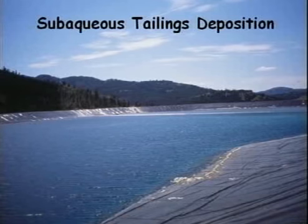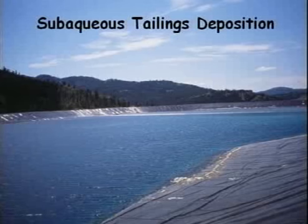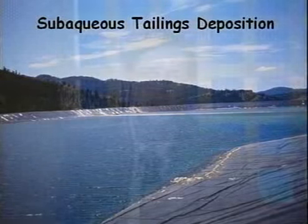It's important to make sure that the submergence is permanent. Periodic drying and re-wetting is the worst possible situation and must be avoided completely to make this particular methodology work. Tailings submergence may be an acceptable method to control ARD in the majority of tailings basins, but the conditions in the tailings impoundment or the dam itself are typically not conducive to total flooding.